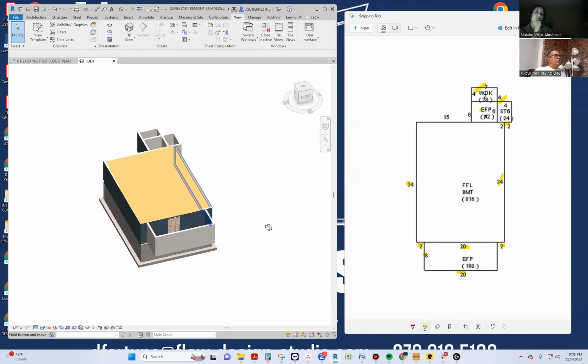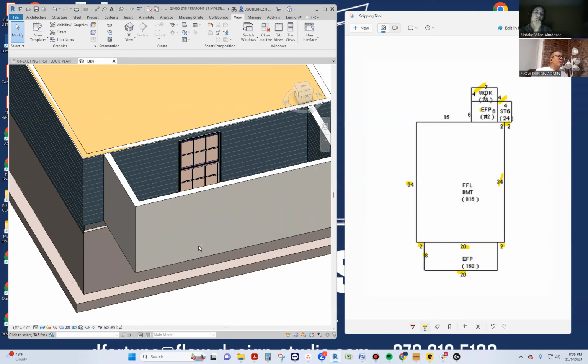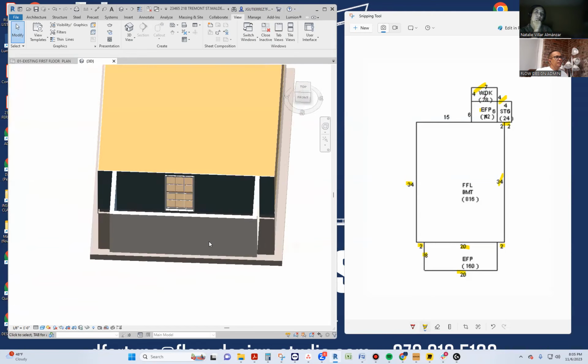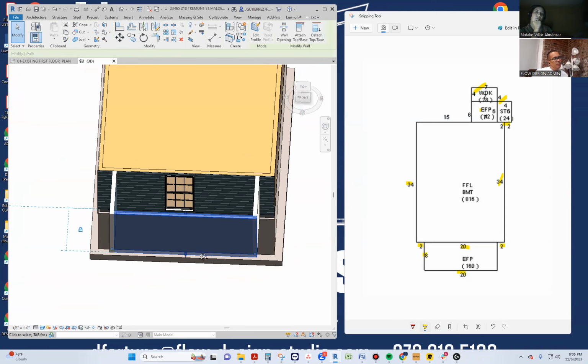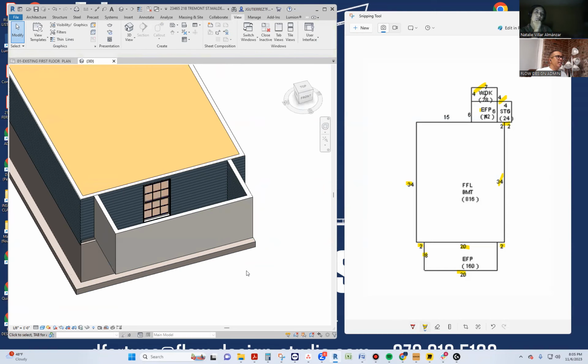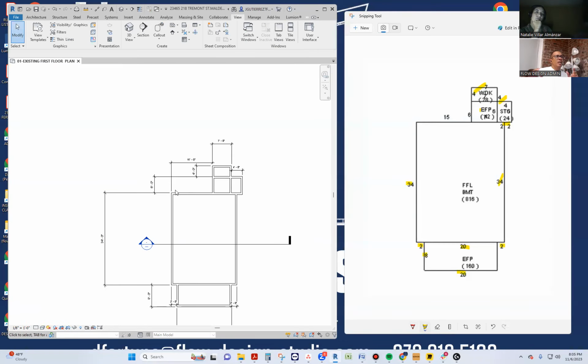A couple things I want you to be aware of. The way you draw things, meaning this is the interior of the wall that's facing the outside. That's technically wrong. So at some point, it's going to have to be fixed. I use the phrase 'we're going to do this later' a lot, but this should not be done later. Make sure you draw your walls facing the right way, knowing what is the outside and what is the inside.